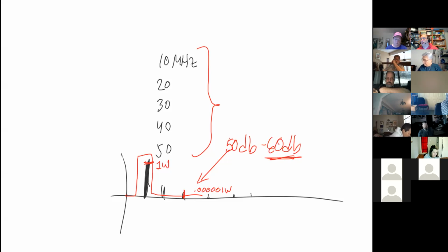This can be caused by other things that are going on in your amplifier circuit, because every amplifier can act as an oscillator. There might be something that's not harmonically related, like one over here and one over here. Spurious emissions also have to be knocked down by filtering to those levels that make it legal.